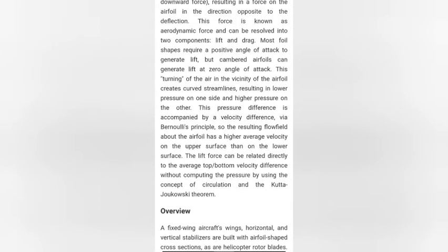This pressure difference is accompanied by a velocity difference via Bernoulli's principle, so the resulting flow field around the airfoil has a higher average velocity on the upper surface than on the lower surface. The lift force can be related directly to the average top-to-bottom velocity difference without computing the pressure, by using the concept of circulation and the Kutta-Joukowski theorem.